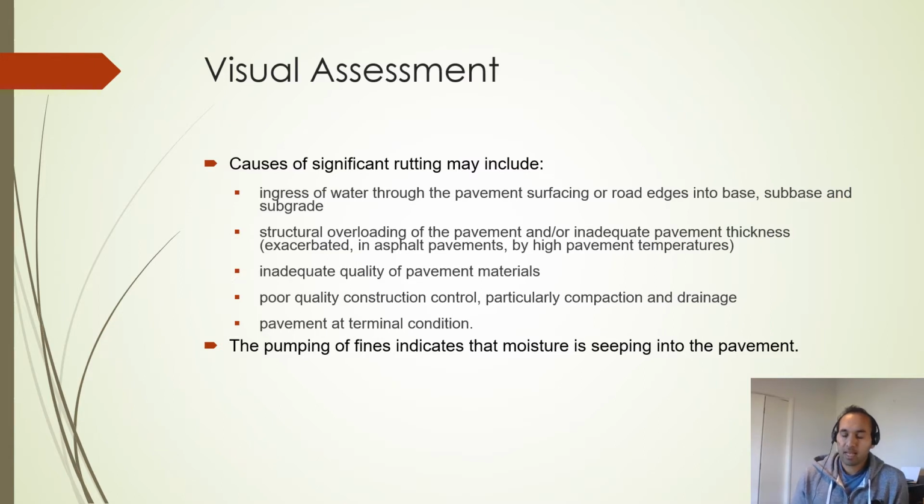The other thing that's been noticed on this pavement is pumping of fines. You get pumping of fines when water gets into the pavement. Those fines in the crushed rock can start coming to the surface. So it's more a result of what's happened prior to it. The pavement's cracked up, water's now getting into the pavement, and the fines are getting pumped up to the surface.